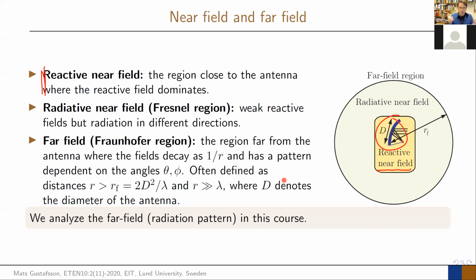That is what's producing these things of SAR, specific absorption rate, which we will talk about later, which means that we have restrictions of how much power can be transmitted close to a head, for example, because our head will absorb this and eventually get warm. And it can, in some ways, injure us if the power is too high. And every device that is sold is forced to satisfy regulation, which means that the power has to be sufficiently low, so it's entirely not dangerous for us. So that is what SAR is, it's standardized. And that is because we sit so close to it.